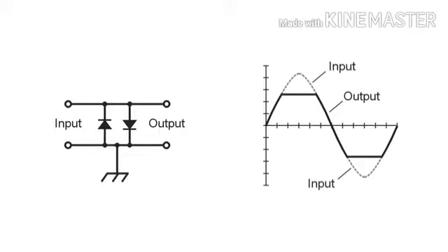About a phenomenon known as diode clipping, or audio clipping with the use of semiconductor diodes, how you can use two diodes back to back. Ordinary rectifier diodes will work at audio frequencies to limit the amplitude of the audio output of a device such as a communications radio.